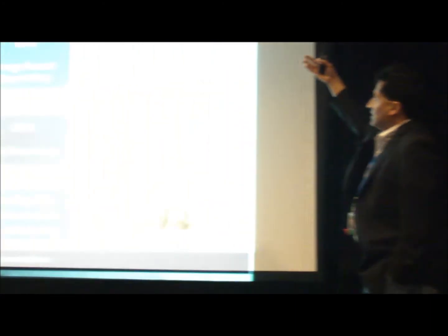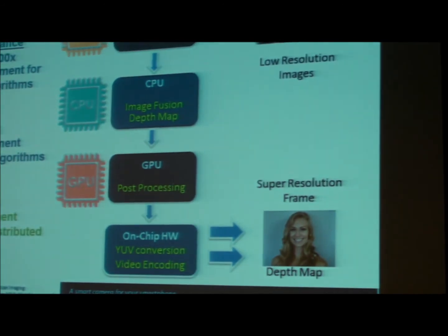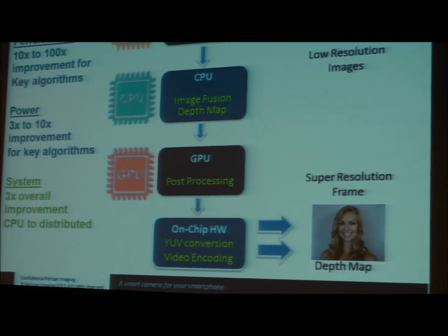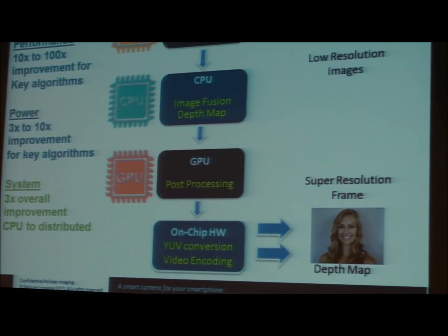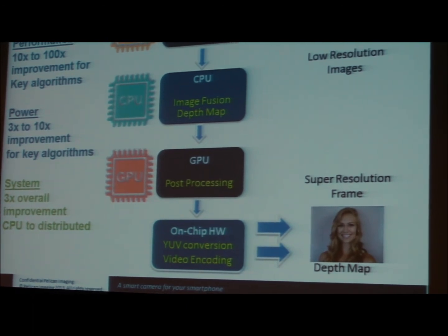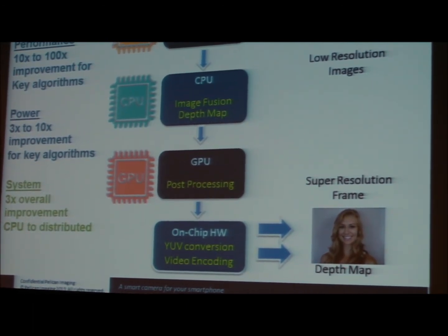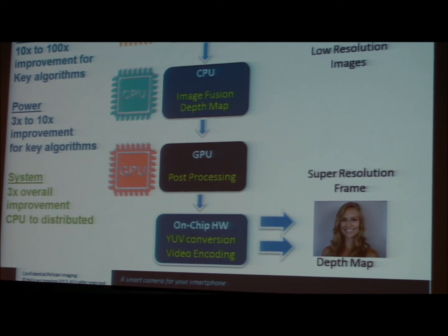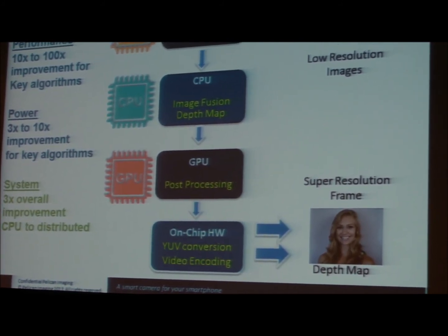We really have three or four main stages in our pipeline. The first stage is what we call our normalization stage. This is taking the calibration data you normally have with the camera that's built at manufacturing time, and normalizing that data to take into account that you've got 16 different cameras, and every camera is always different. In fact, every camera and every phone is always different. Every sensor is unique. There are pixels that may not be there. There may be cluster defects. The lens will always be slightly different within some tolerance that we've worked with manufacturers.